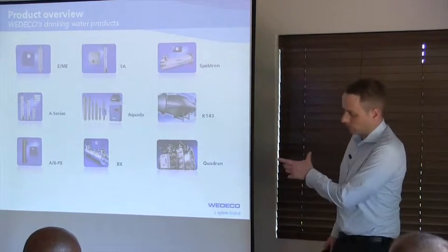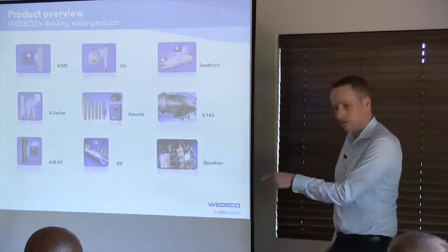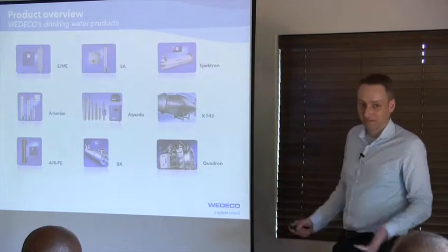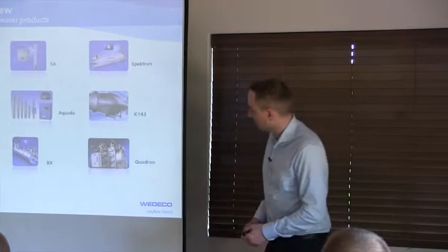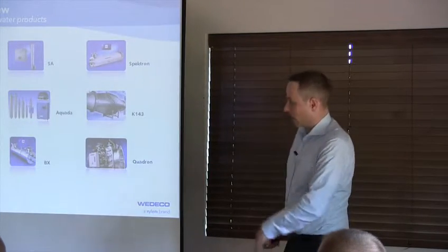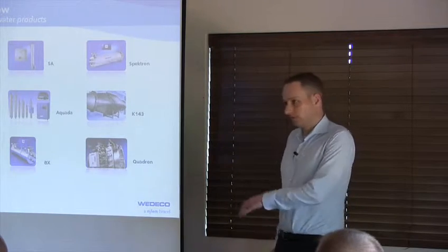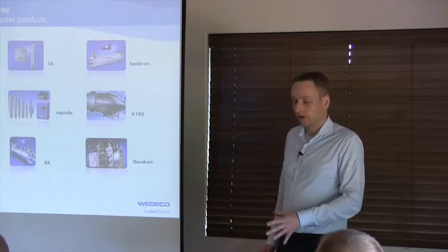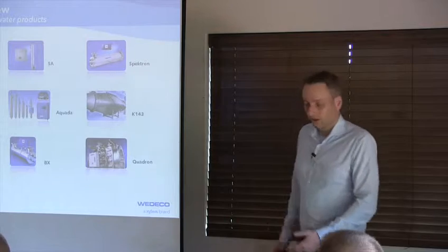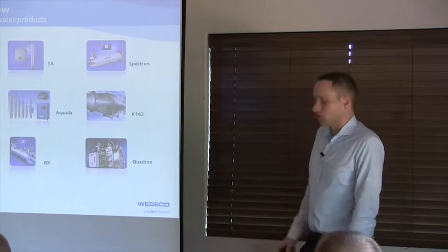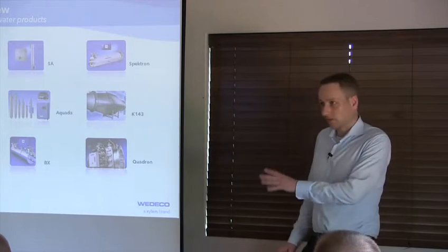So after 1 centimeter from 100 watts, there's only 17 watts left, and after another 1 centimeter, basically nothing. Secondary treated wastewater is normally between 45 and 55% UVT, and for tertiary, depending on your pre-treatment step, something between 60 and up to 75.